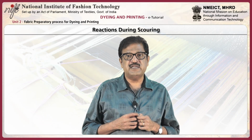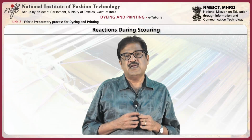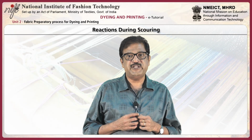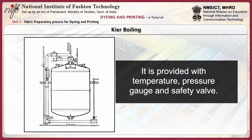There are different methods normally being used for scouring the cotton material. Let us discuss the conventional process of scouring, which we normally call kier boiling. A kier is a cylindrical vessel capable of holding 250 to 500 kgs of fabric. It is provided with temperature, pressure gauge and safety valve.